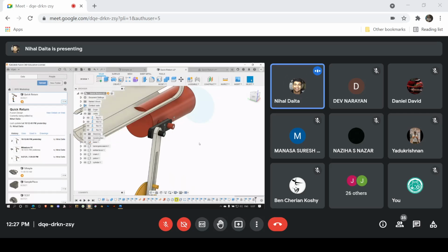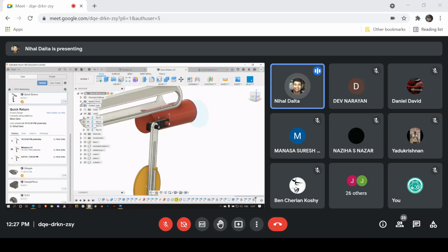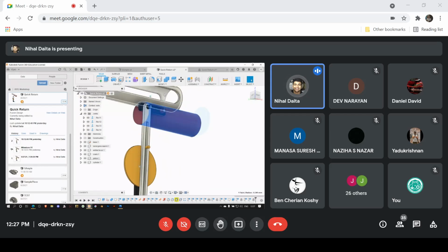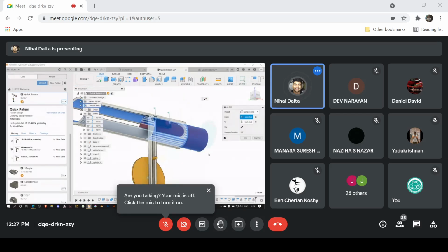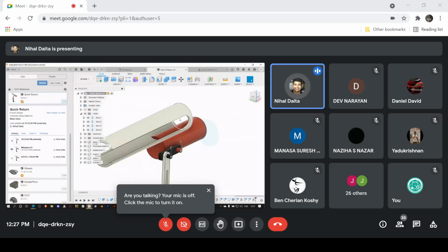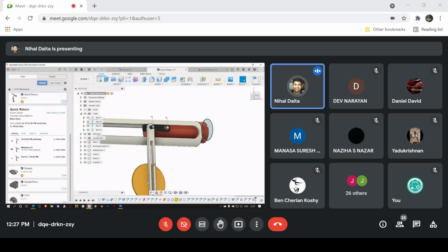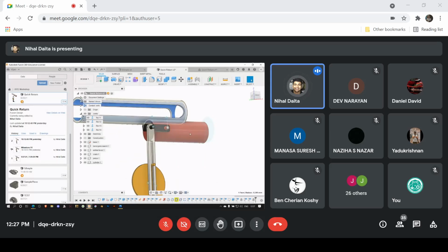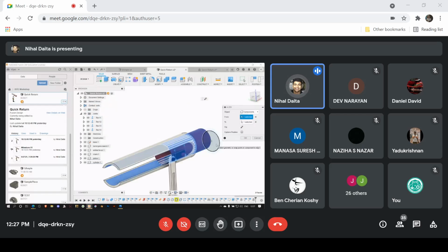It's just stuck. That's fine. Okay. Now this outer cylinder surface should go into the inner cylinder surface. Cylinder should go to the outer. So it goes from to to approach, right? If you want to move this to this, you click on this first, then the second. I shift click those, then I click Shift A, which is for align, and it moves it to that position. And let me just capture position.